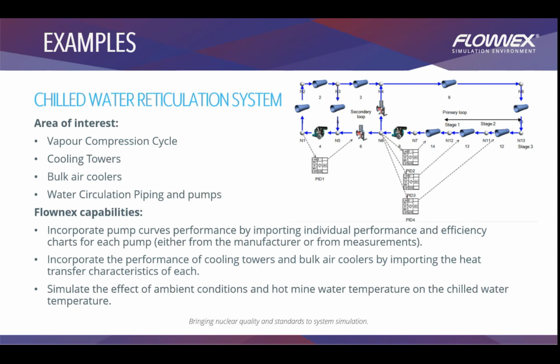in Flownex as well. You can also simulate the effect of ambient conditions and hot mine water temperatures on chilled water temperatures. That means you'll be able to play around with temperatures to see how the water that you're busy distributing or recirculating will be affected. Will it change its phase or not? So you will also have the control analogy in Flownex that you can use to control the water that is being distributed along the pipeline through valves or orifices or pumps as well.